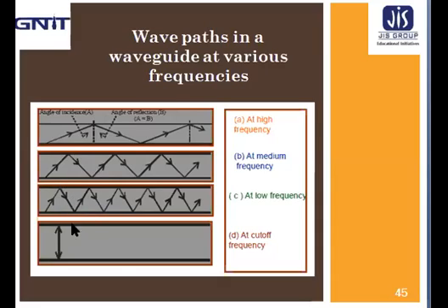Now, when the operating frequency reaches the cutoff frequency of the waveguide, the signal simply bounces back and forth directly between the side walls of the waveguide and has no forward motion. At this cutoff frequency or below it, no energy will propagate.